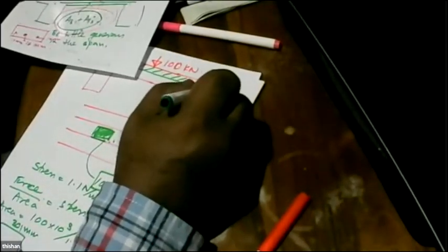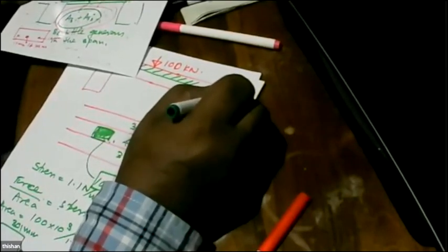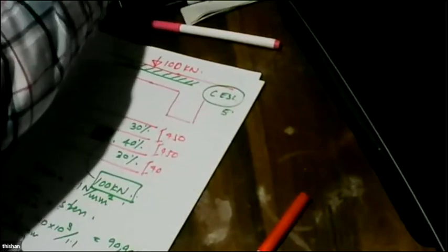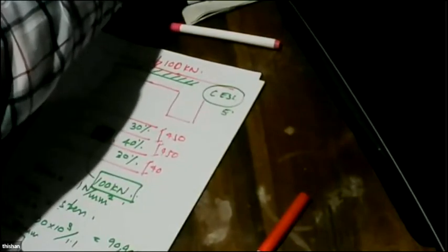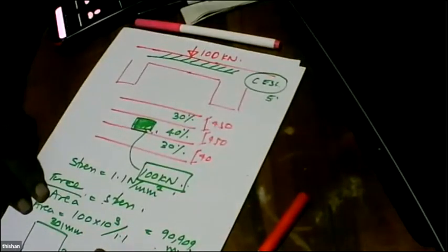And there's some other load called knife edge load that will act simultaneously, so that also has to be considered. So basically, first consider the live load scenario due to designing it for HA loading, and then, if you want, you can check it for a 100-ton vehicle.